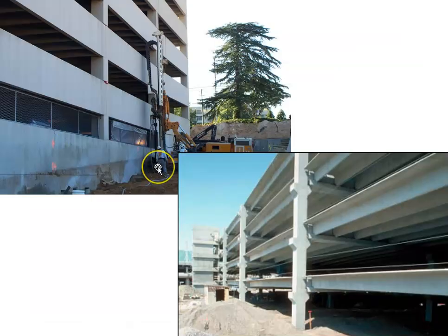And we could actually see that here, where the loading would not be concentric. So here we see a parking garage column. It is under construction, so right now this column is only loaded from one side, and that again will create that eccentrically loaded condition. And all columns on the perimeter of a building would, of course, be eccentrically loaded because the floor is on one side and nothing is loading it from the other side. So all peripheral columns are eccentrically loaded.